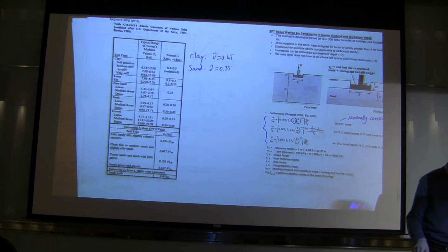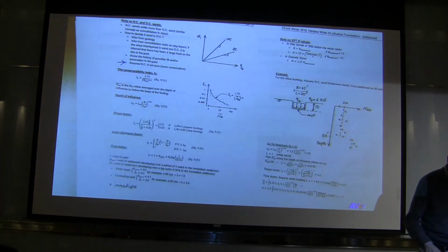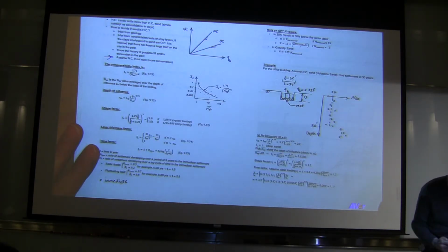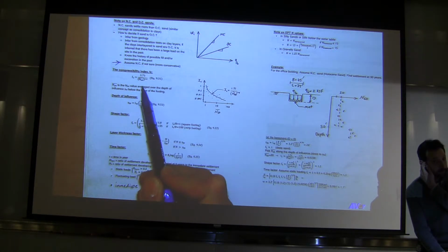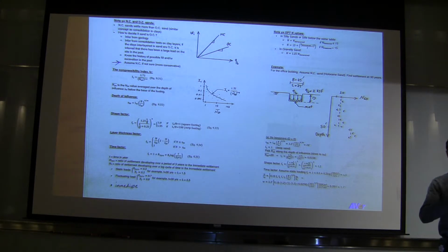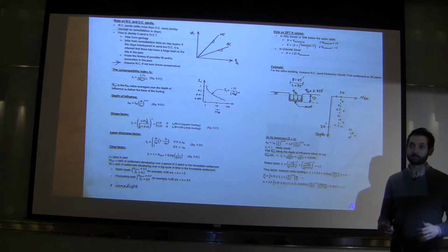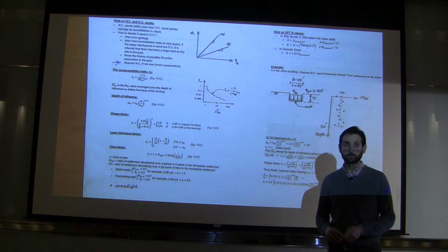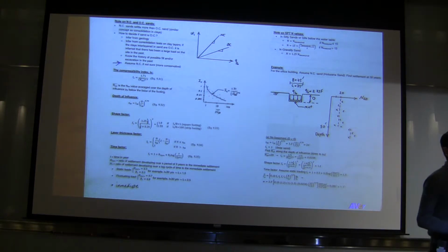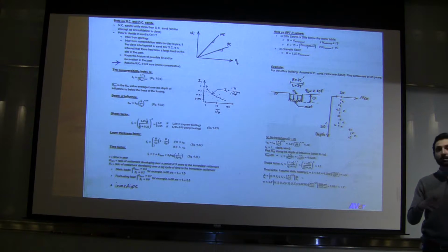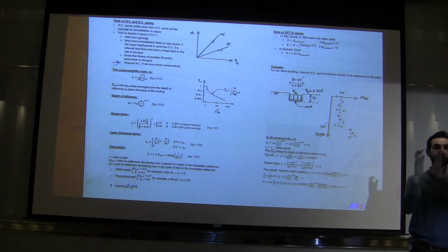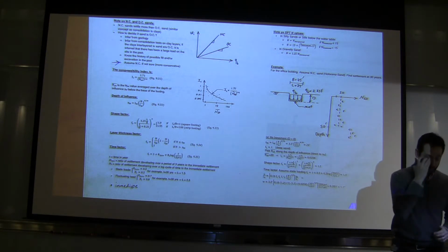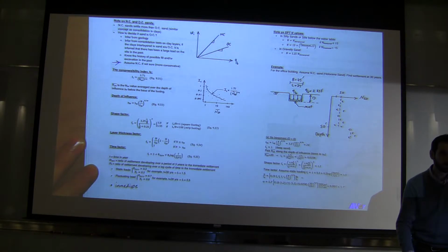And you can see that in the equation that we have on page 13. So if you look at I sub c here, if your sand gets stronger, your average N60 below your foundation should also increase, and that will reduce I sub c, and that will reduce your settlement. Okay? So again, do the same thing when we get to the clay equations too. I want you to compare everything to the elastic solutions and try to find those key variables. Any question before we move to the next one?